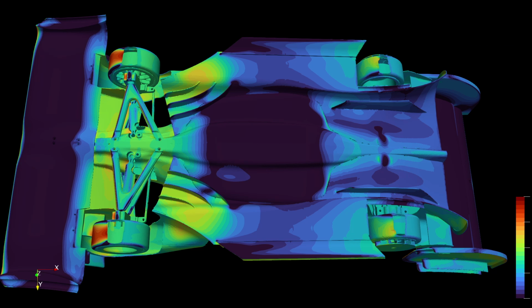So I want to start with the underfloor because this area has the ability to generate a significant amount of very efficient downforce for the car. This picture here is a coefficient of pressure rendering of the RC Hypercar's underfloor. The coefficient of pressure is very similar to a coefficient of drag, where it's a unitless way of measuring pressure so that we can easily compare two pressure plots against each other relatively so that the colors and everything align.